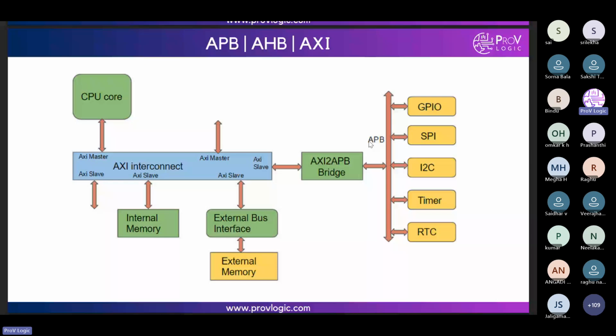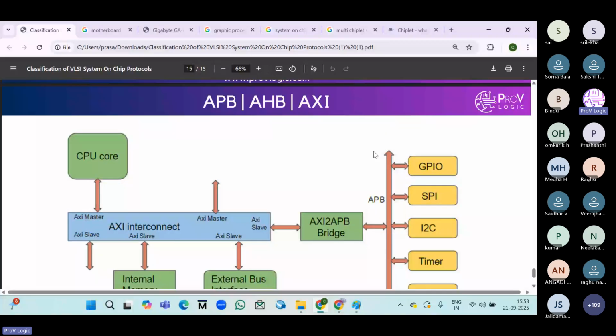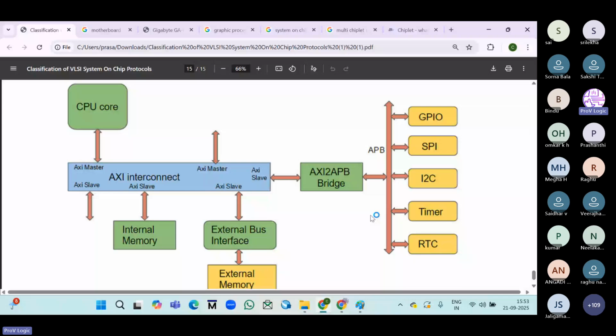If you want to self-learn, you need to understand the entire specification first. That means what the signals are. For the APB protocol, we have signals like clock, reset, address, data, write, read, PPROT, PSLVERR, PWRITE, and wait state. So first of all, you need to understand these, and there will be some waveforms. Like I can show you.